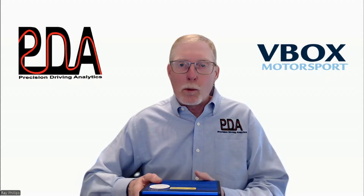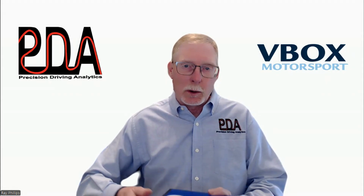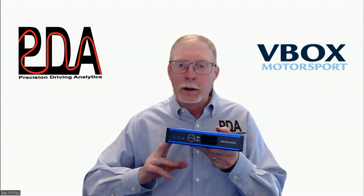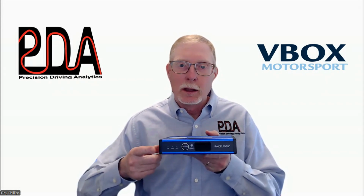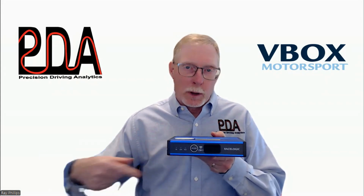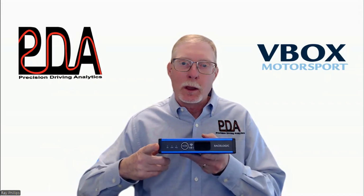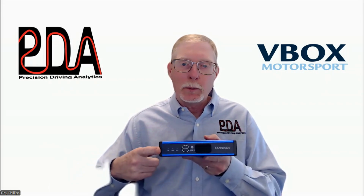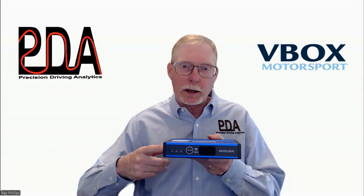Once the scene is loaded on the SD card, you want to make sure that your HD2 system is fully booted up. The OK light should be solid green, and that's the one on the far left here. Once you plug that SD card in, that light should start blinking rapidly. Other lights are going to flash as well, but that one pretty much continues to blink rapidly until it fully loads the scene.